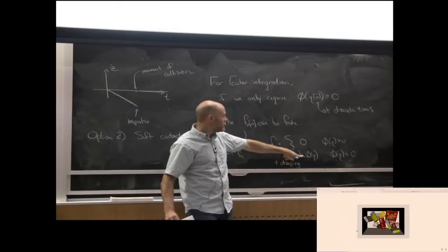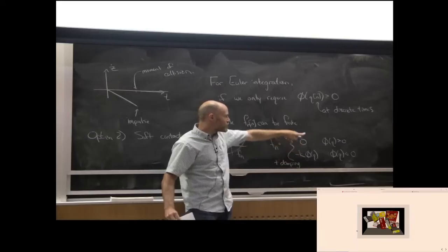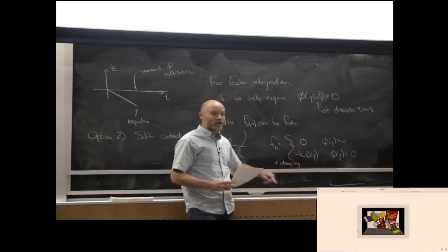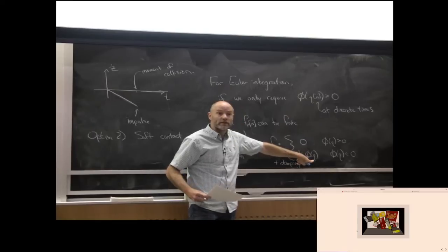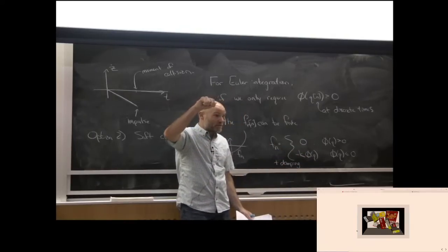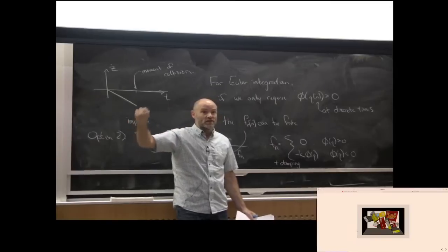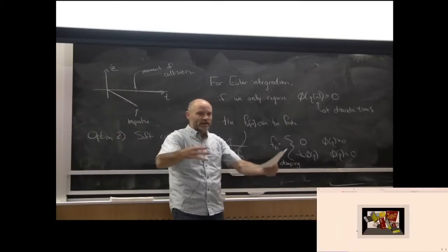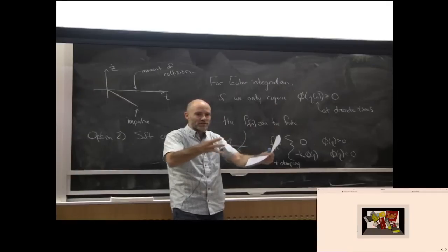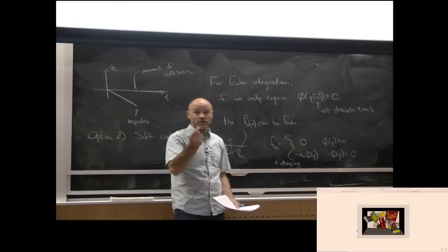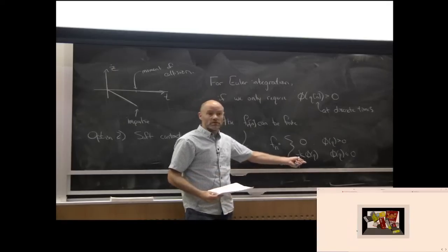Even worse, the stiffness of the simulation is in some sense changing as a function of the configuration. So it's hard to pick one time step that will work in all of the regions, because the stiffness values are different in different regions. If I get an object jammed between multiple objects, that's a different configuration. It's much harder to pick a single h that works for all the possible derivatives you're going to get across the states.